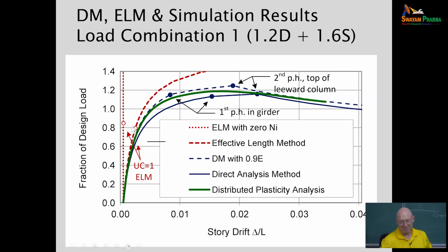So the effective length method here is basically saying that with the notional load in AISC, you can only get 80% of what we wanted to apply on this frame. Now, of course, our fancier second order inelastic solution is telling us we can get close to 20% more than the load that we were looking to design for.